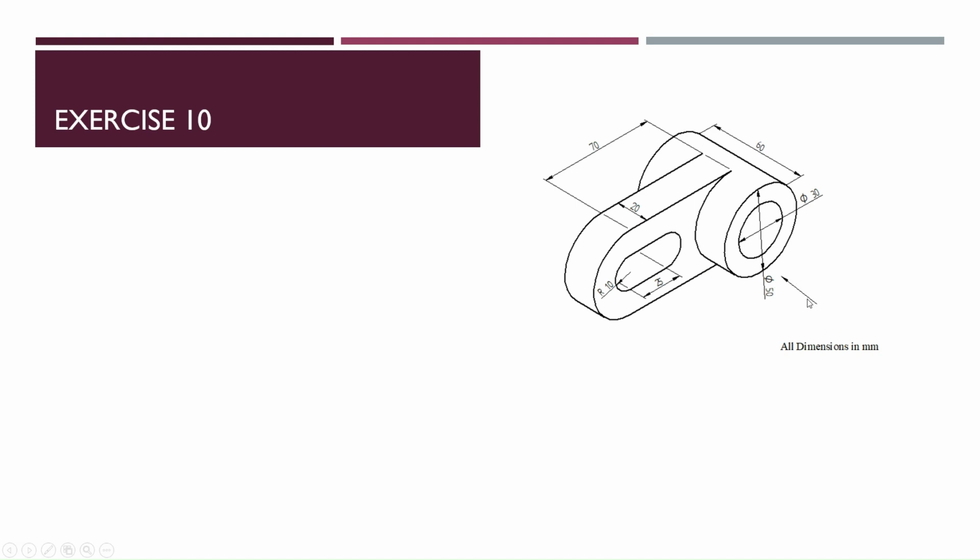So this is the direction in which the observer is going to look. In the front view, I'll be able to see a circle towards the extreme right with two concentric circles, and also a rectangle with a semicircle towards its extreme left with an elliptical hole as shown here. So this will be the front view. In the top view, it will look like a rectangle with a rectangular protrusion. In the side view, the observer will be able to see this length overlapped by a rectangle block of 20 mm cross 50 mm. So these are the observations. Now let us see how to create the 3D part model.